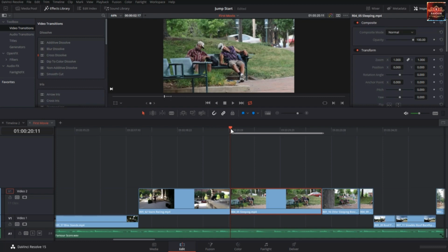So let's say after 1 second, so I will use Shift right arrow to jump 1 second. And then at 1 second, I want the position to be just over here. So I will click on the keyframe and a keyframe is created. Notice I'm on top of the keyframe now, it's red. You also notice that in the clip here, you already have access to the curves and the keyframe editor.